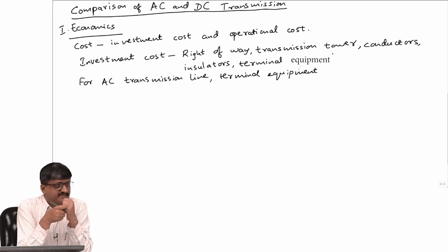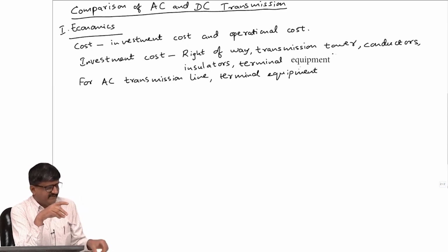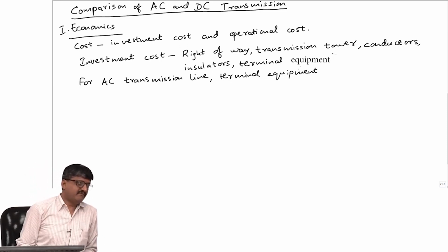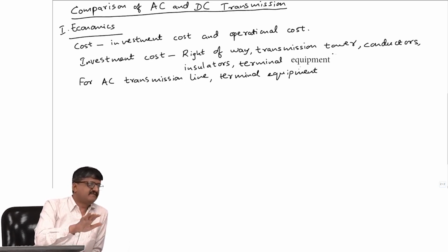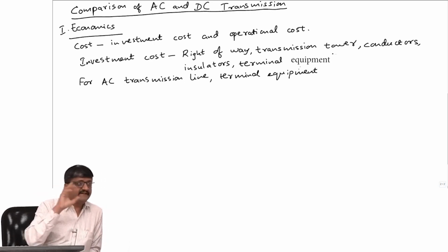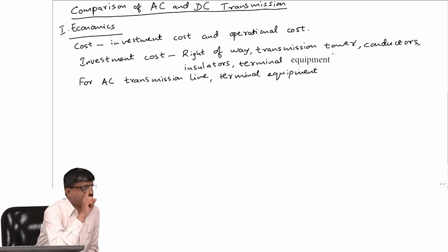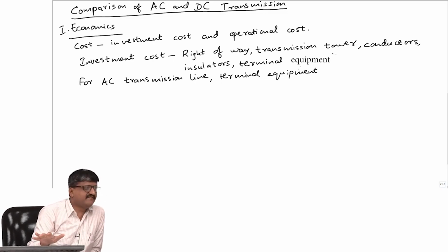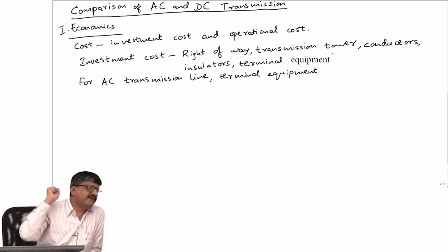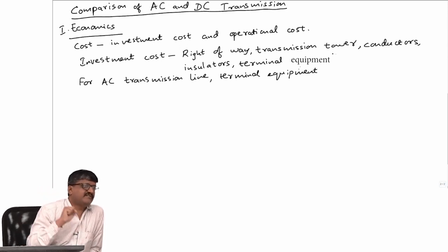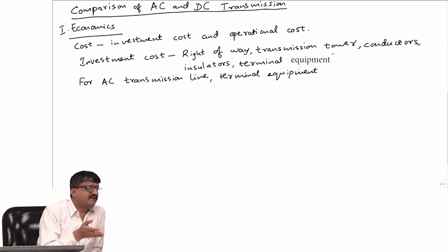See, a transformer is usually an equipment that is required if I want to connect a generator to the network or a load to the network. If I take one transmission network consisting of many transmission lines at the same voltage level, there is no voltage transformation anywhere. We need transformers for many purposes. One example is, if I want to connect a generator to the transmission network, I need invariably a transformer. Now I am not considering that part here. What I am trying to say is, in an AC network, take one particular transmission line. It is not necessary that I will have a transformer in any transmission line. Take arbitrarily any transmission line. At both ends I will not have a transformer.